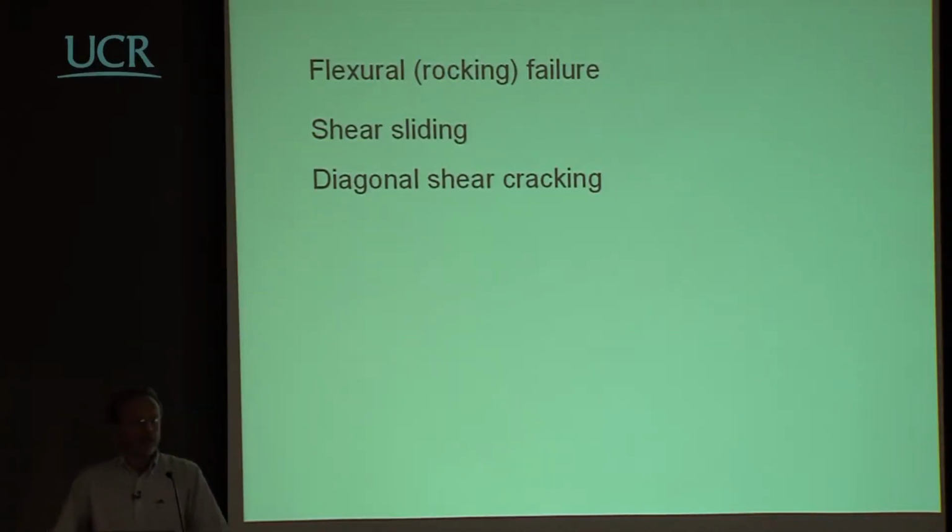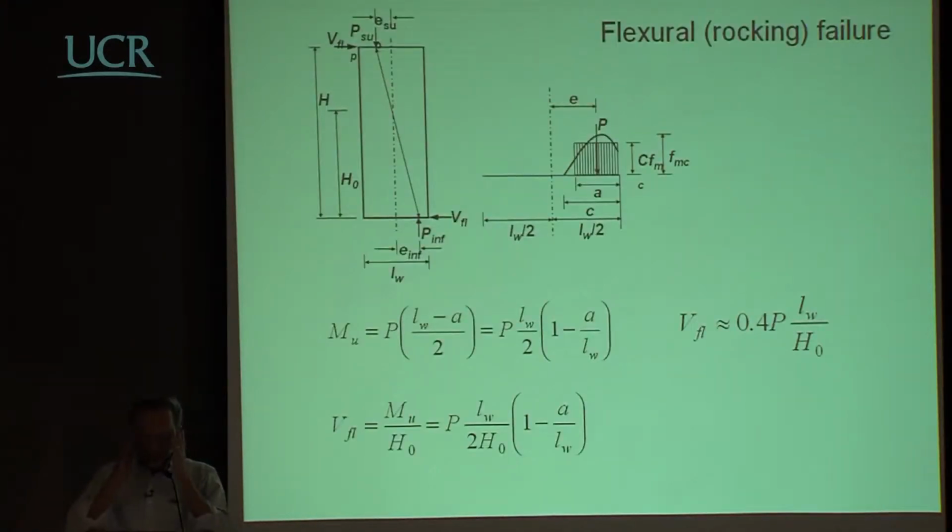And if you want to think about these possible damage mechanisms in the frame of displacement-based design, we need for each one of these to define the rotation capacity or the drift capacity, however you want to call it, and the equivalent damping, and essentially to go back to the main frame that we have been discussing.